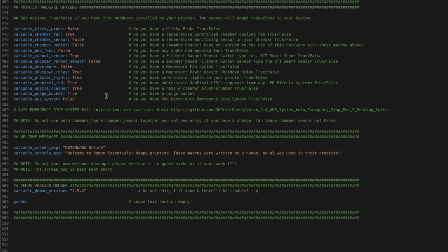And also, if the nozzle only just slightly misses the end stop switch, like if it kind of touches on the edge, or the heat block triggers it, if it's only a few millimeters out, this will completely throw off the Z level for the printer. So when it starts printing, it will try and put the nozzle through your bed to the level it was when it homed.